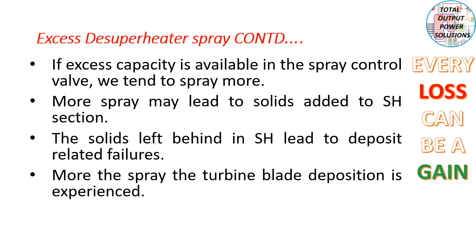Now if excess capacity is available in the spray control valve, we tend to spray more. More spray may lead to solids added to the superheater section. The solids left behind in the superheater lead to deposit-related failures in boilers. The more the spray, the more turbine blade deposition is experienced in the turbine.